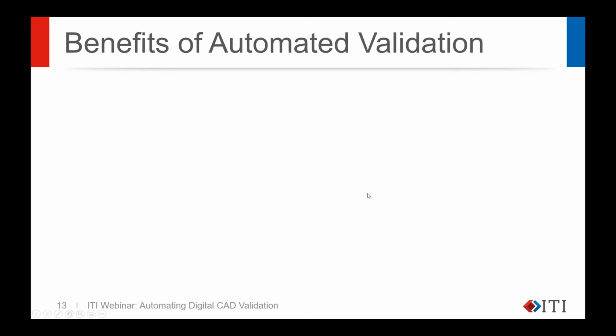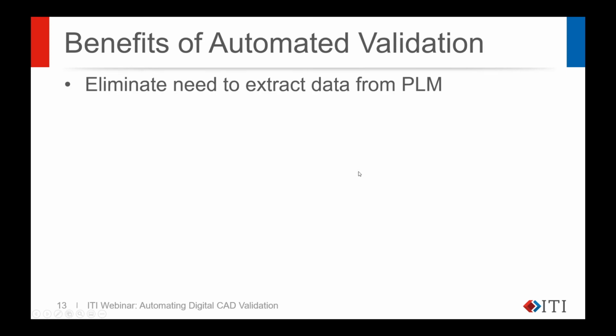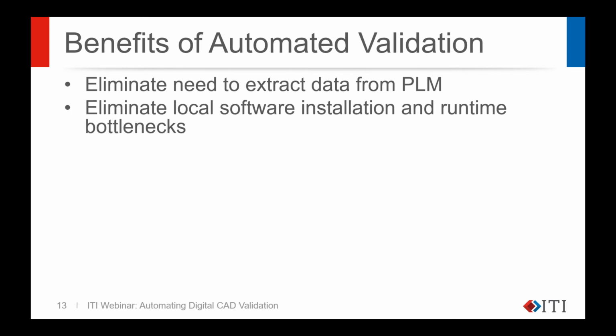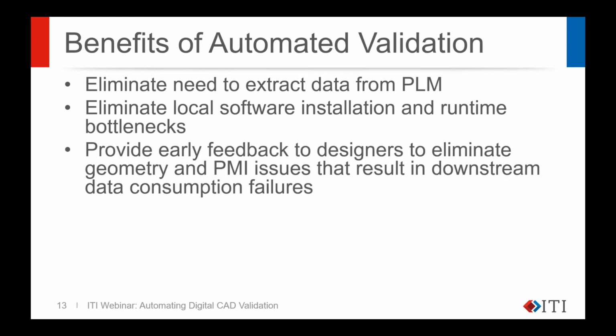So all of that said, I'll wrap up with the benefits we've seen in automating the CADIQ tool. The big one is eliminating the need for users to do non-value-added work like staging data and doing the runtime. So no software installation, no waiting for an analysis to complete because it's happening in a queued manner on the server. This can enable people to get better early feedback in the design stream and take care of things. A lot of the issues may exist in the data and don't change a lot from revision to revision, so finding them early is very helpful.